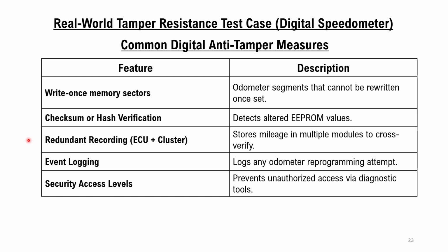Redundant recording in ECU plus cluster stores mileage in multiple modules to cross-verify. Event logging logs any odometer reprogramming attempt. Security access levels prevent unauthorized access via diagnostic tools.